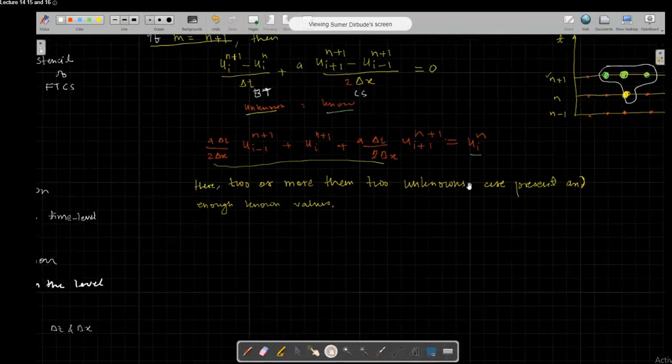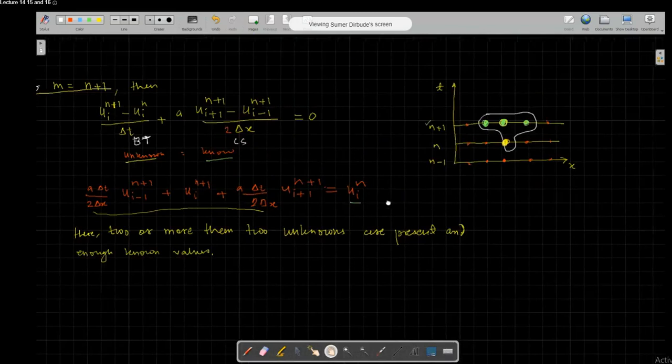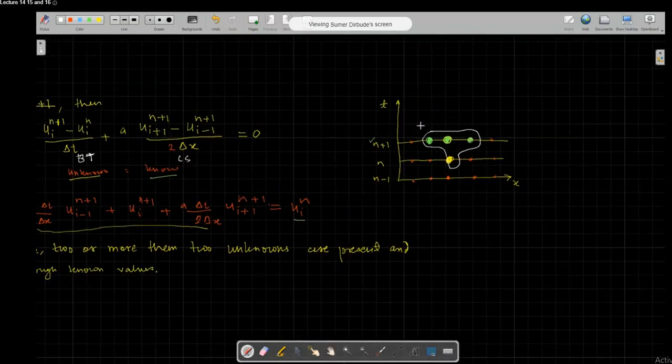As you wrote for forward in time, here all our discretization at space level is at the n plus 1th level, and hence it is called backward in time. All our calculations are done backward in time. We are calculating for the present time and picking the value, whereas before we were trying to calculate the future value with present values.